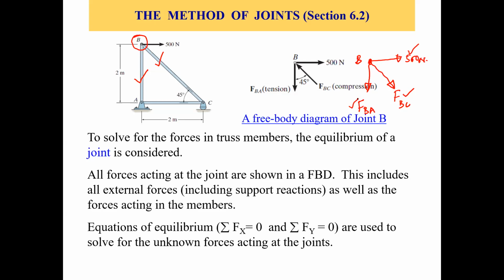So this was the joint, this is the external force, this is the member force, this is also the member force. Now, to assume the member forces at any joint, we can simply take tension in all the member forces, right? Now, FBC, if you look at FBC, this arrow is pulling the joint. So it's a tensile force. So we assume that it's a tension force.